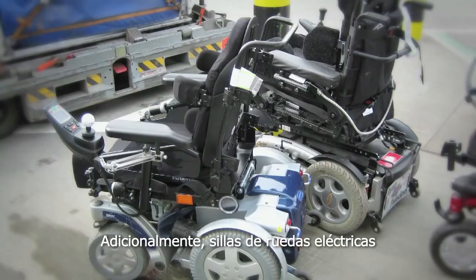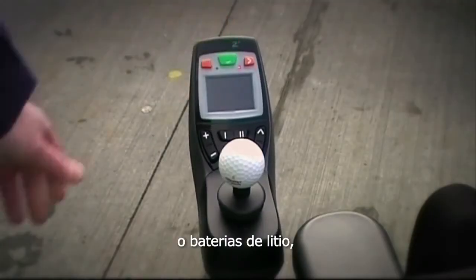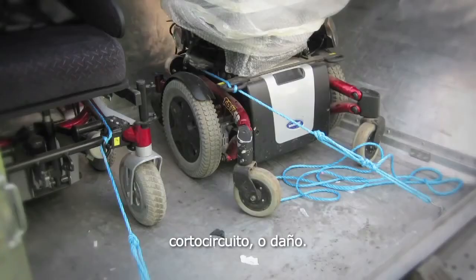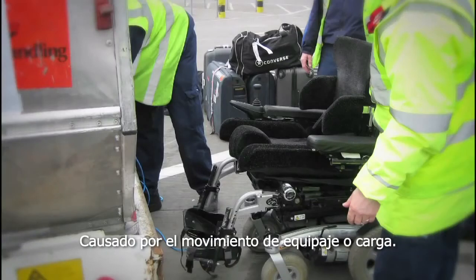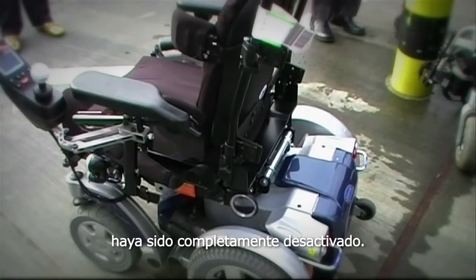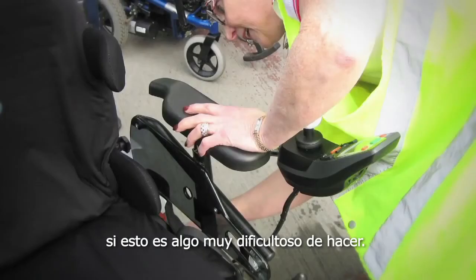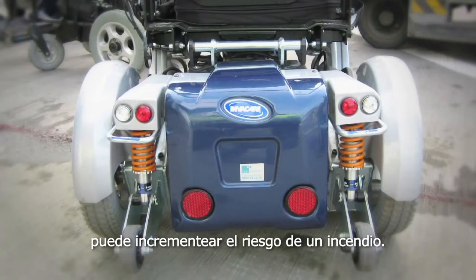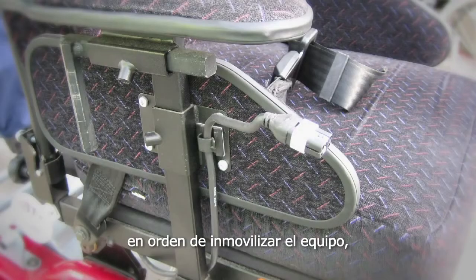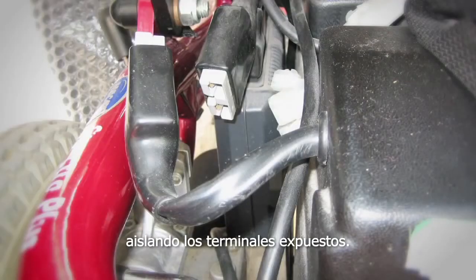In addition, electric wheelchairs or mobility aids powered by either non-spillable or lithium-type batteries must be protected from inadvertent operation, short circuit or damage caused by the movement of baggage or cargo. Prior to loading, make sure that the device has been fully deactivated. Disconnecting or removing the battery is not required, since this can be very difficult to do and, if not done properly, can increase the risk of a fire. If that is the only option, in order to immobilize the device, make sure the battery is protected against short circuit by insulating the exposed terminals.